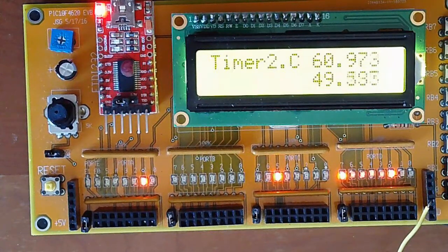The bottom rung is my counter. Every time I interrupt, I'm going to increment a counter, then display it. And here you see the time is displayed to every 1 millisecond. The upper one is every time I loop, I count. The loop is really, really slow. That means the main routine is not keeping up. That doesn't matter. The interrupt runs in the background. The interrupt isn't affected by the main routine. Every millisecond, the interrupt is being called and increments a counter. And the main routine then displays that counter. That's my time in milliseconds.